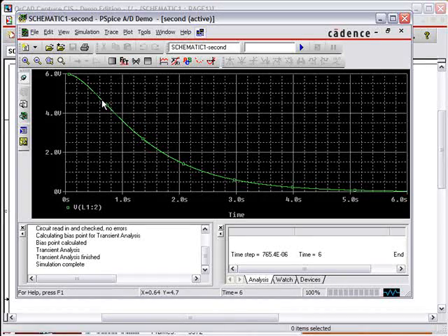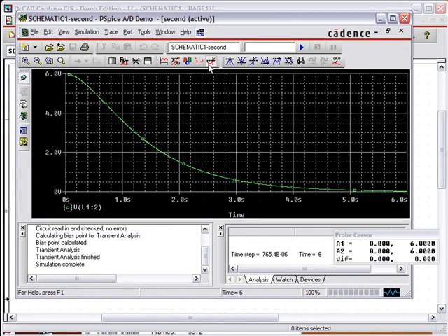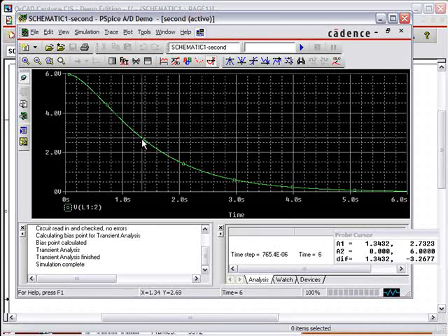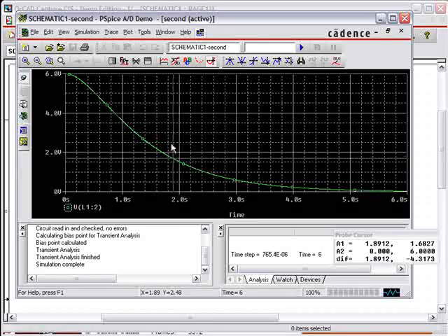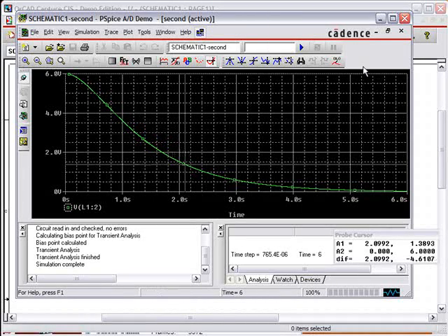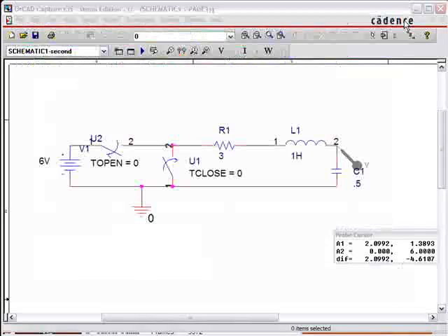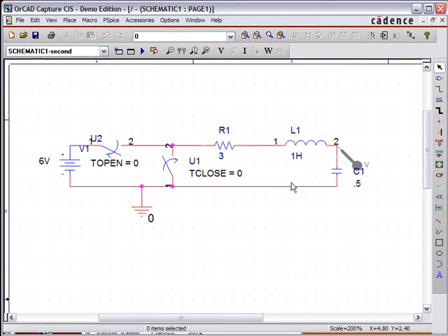So we can also, if you have a problem to solve, compare the answers. It's really hard because there is no way we can get an equation. So what you can do, you can solve this equation and then solve for the circuit, and then plug your equation in your graphing calculator, and then graph your answer. Then you can compare your answer to the answer you got in PSpice by comparing the points right there and tracing them on both calculator and your PSpice. That's it.